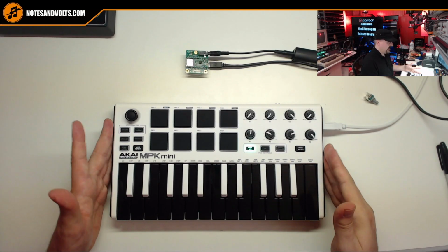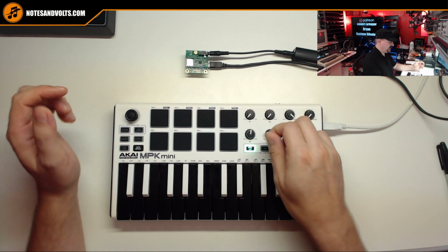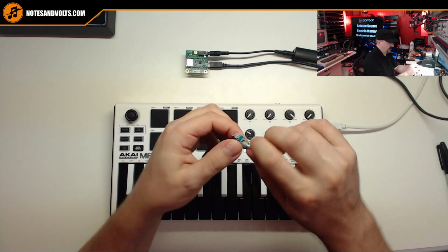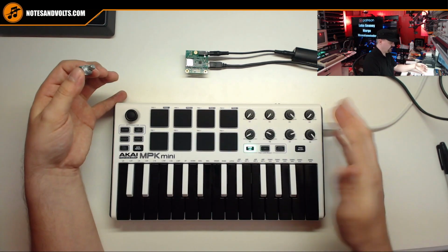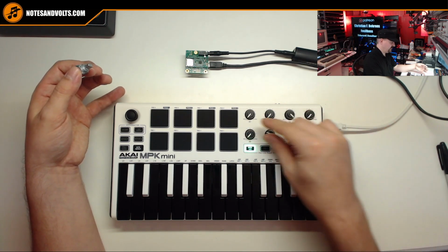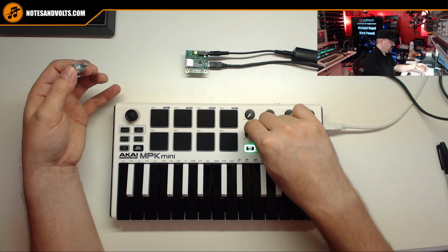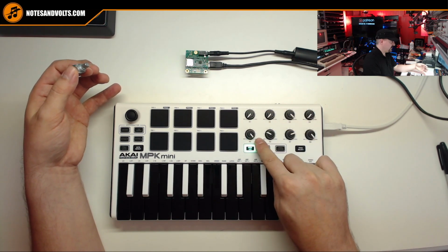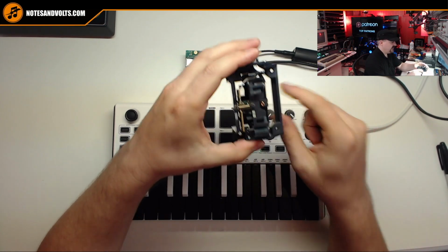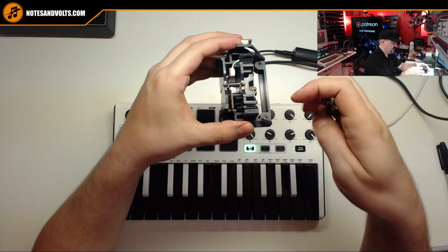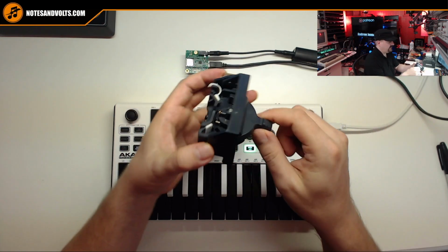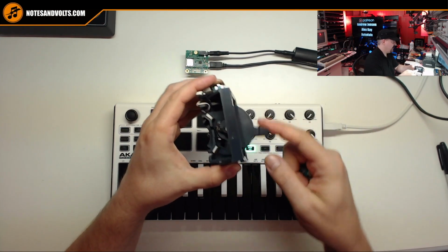Now, if we looked inside this MIDI controller, you would see that these controls are actually potentiometers. And when I turn it, the controller is reading the position of the potentiometer and putting out a value of 0 if it's fully counterclockwise, up to 127 if it's fully clockwise. Now, if we took a look at a pitch wheel from a controller, you'd see that there's actually a little potentiometer in there. Probably this exact model.